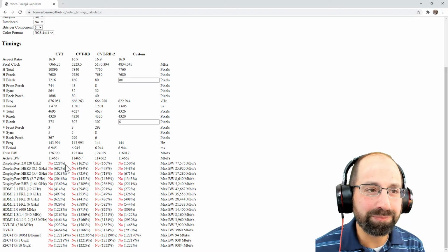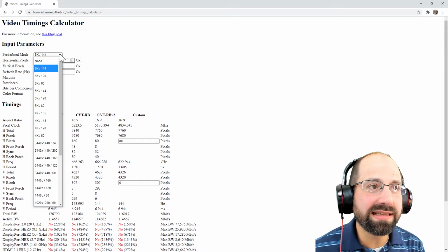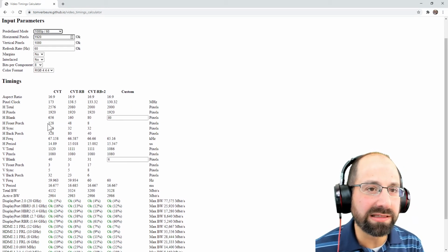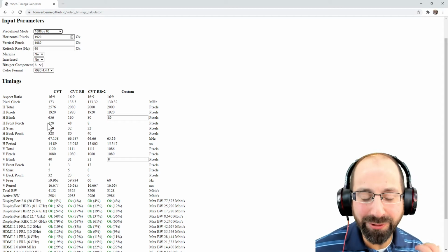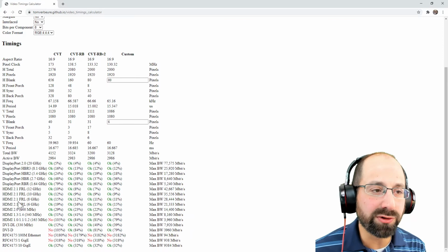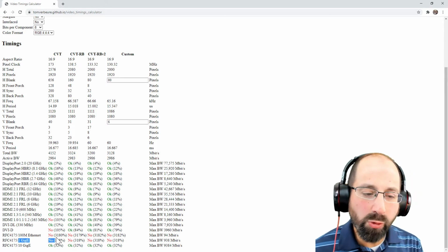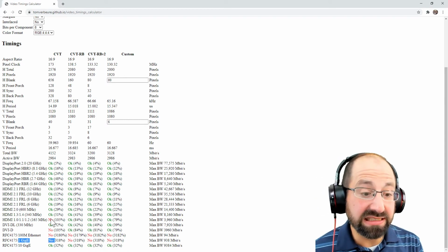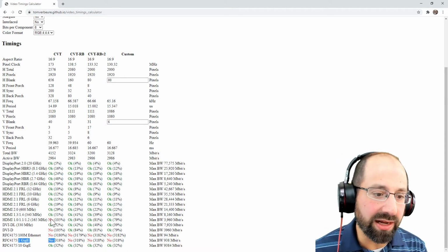So for our purposes, we're going to stick with what we used to call full HD, this 1080p 60 hertz frame of reference. That should be okay for our DDR2 memory on the board. And it should be okay, of course, for displaying this on the attached monitor. And even when we want to display a lot of that information and copy it over our gigabit Ethernet, we're not there, but it should be close enough to do reasonably decently over that gigabit Ethernet.